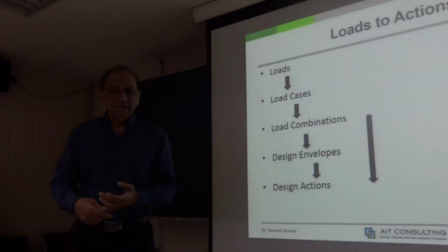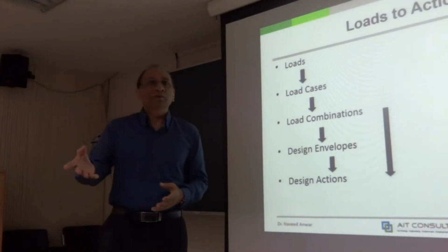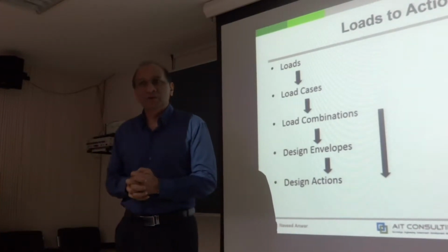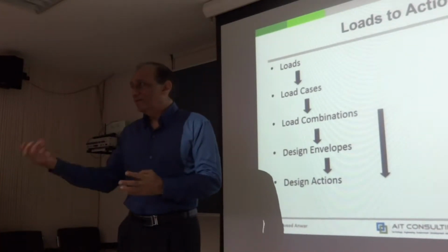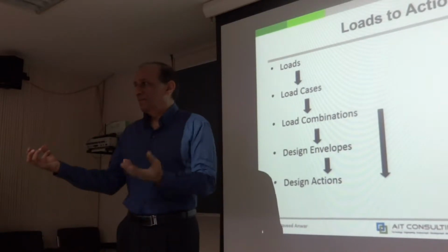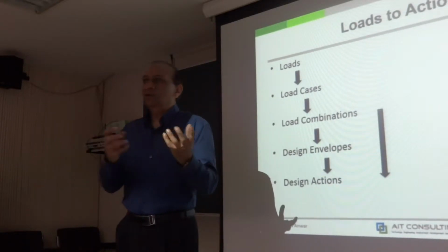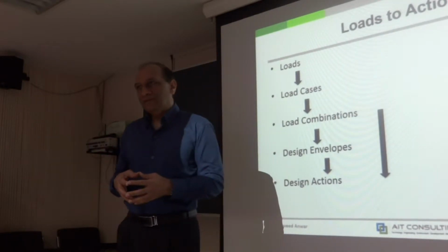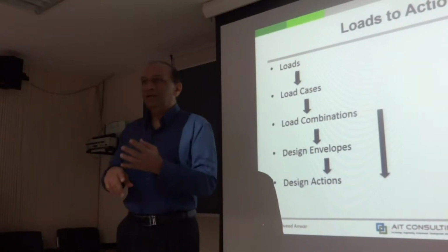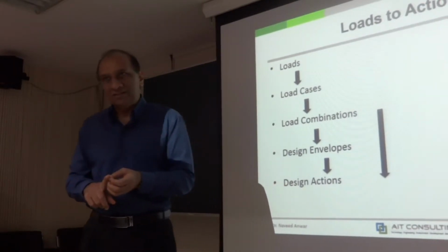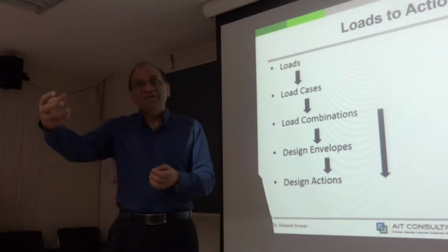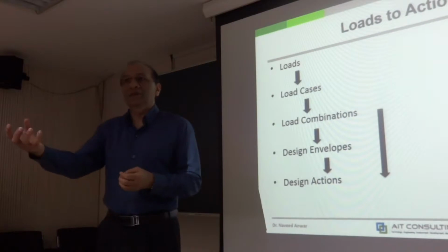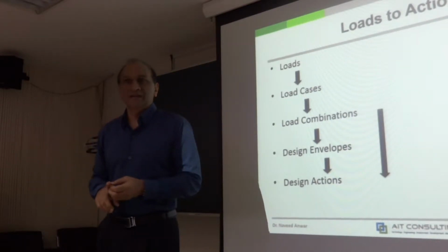You say the dead load here, or the live load, let's say live load. You say the live load here is 40 pounds per square foot or 2 kilonewton per square meter, right? But the reinforcement is not calculated based on this load number. This load number must first be applied on the members, transferred to various members, and then you calculate bending moment, shear forces and all those actions. Then they are combined, multiplied by some factors, combined with some other possible loading, and you come up with a number for which the reinforcement will be designed.